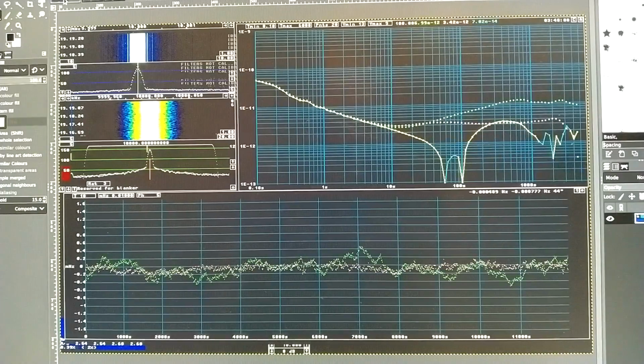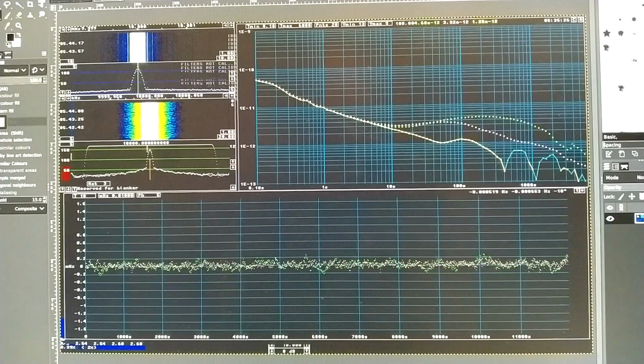So I can set 44 kilo ohms for channel 2 and 2.2 kilo ohms for channel 1, which means I will force it to have the modulation of the rubidium oscillator. But still the channels will be uncorrelated at 100 seconds. That's 0.01 hertz, and that's as close as I can go with phase noise measurements.